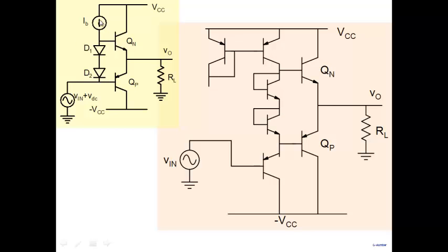Now the diodes were biased at a certain current, I0. Let's say this is my current mirror. If I have a certain current flowing in this transistor here, by mirror action the same current flows over here. And then we've added a PNP part here and driven our voltage at this particular point here, Vin. Can you see that what I wanted was Vin plus VDC. So this is Vin, and what is the voltage here at this point? Vin plus VDC was how much? 0.65. So I get again 0.65 or so.